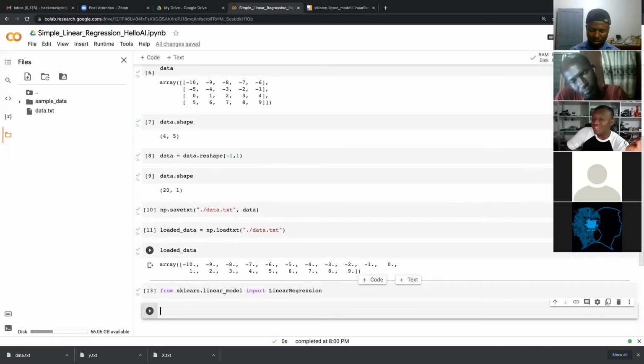Voltage is the thing that you know how to readily generate. I mean, I can just put my bench power supply, set it to any voltage, and I get a voltage. I don't need to do magic to get voltage. But the RPM is what I'm interested in learning. And I want to learn the relationship between voltage and RPM. So this is going to help you to kickstart your project, even when you don't have your magnetic encoders around.